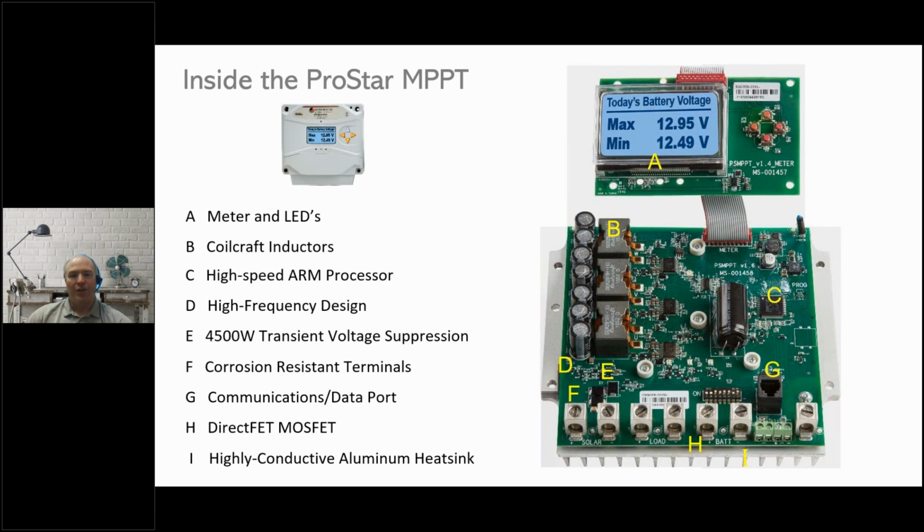The data port on this controller supports Modbus protocol, and the ProStar MPPT has up to 256 days of data logging of battery voltages, absorption charging times, and power inputs and outputs from the controller. We use the DirectFET package for much of our switching technology because of the benefits of cooling, compact design, and reliable surface mount technology. By applying them on the backside of our board in direct contact with the heatsink thermal pad, they stay extremely cool. We use an extruded heatsink design, which contains more pure aluminum than cast designs and ensures very high conductivity.